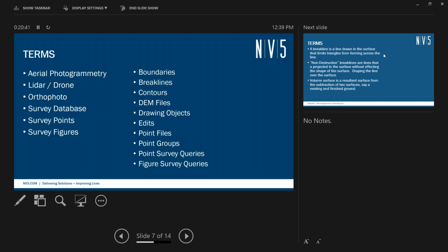Orthophoto. This is an emerging technology as the technology for cameras becomes better. We're going to see more and more of this. This is basically elevations developed from just a photograph, all relative to itself. So this is where the technology is really proving very useful. Currently, the technology is about 2/10 accuracy from just a photograph. No survey control.